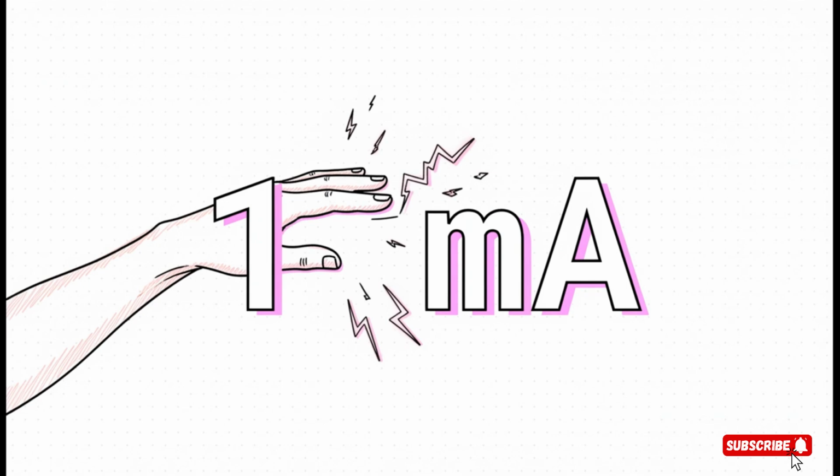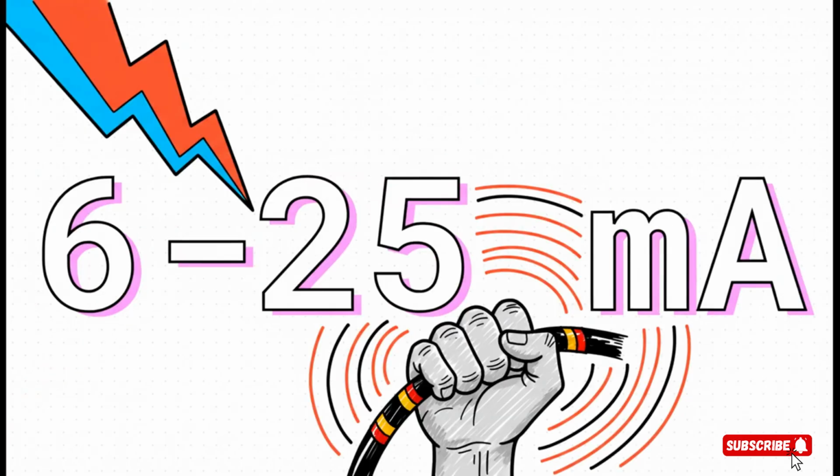It starts so small. At just 1 milliamp, that's 1/1000th of an amp, the human body can start to feel a slight tingling sensation. That's it. That's the threshold of perception. Now let's bump that up just a tiny bit to a range of 6 to 25 milliamps. Suddenly, that shock becomes painful. And here's the really crucial part. This range is higher than what we call the let-go current. That means your muscles contract so tightly, so involuntarily, that you might not be able to physically let go of whatever it is that's shocking you.